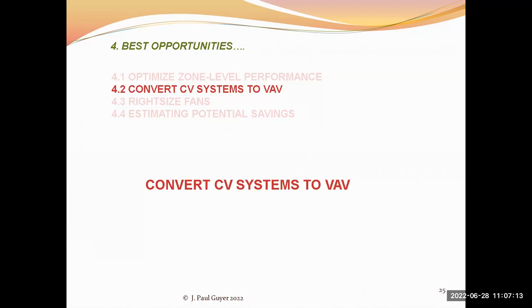When the need changes, when more cooling is needed throughout the building, all of the VAV boxes, each of which is controlled by a thermostat, will tell their VAV box to open up and admit more air to my space. It's getting too hot in here.